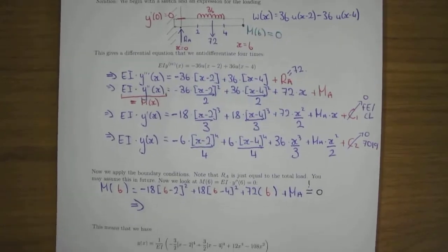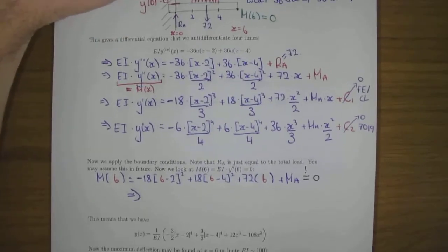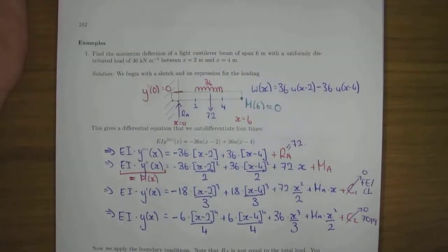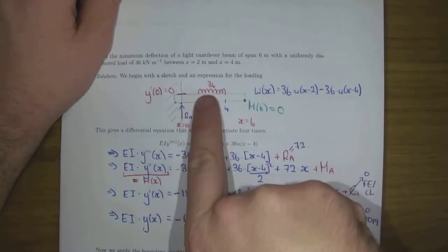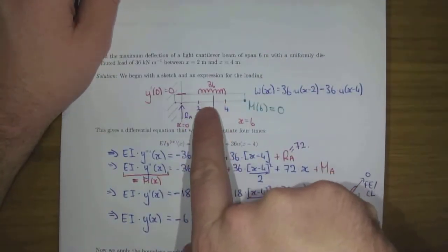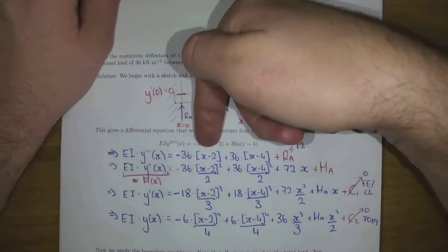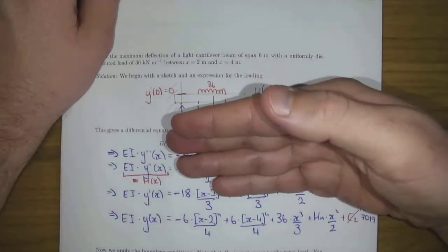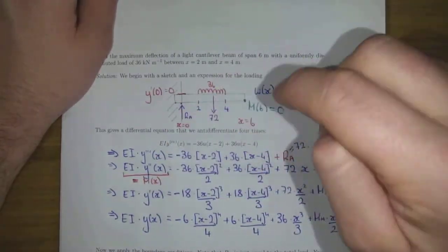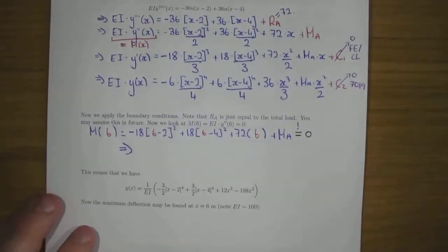Now there is an alternative, as I mentioned on the previous page, about balancing the sum of the forces and the sum of the moments. So if you do know this theory and you end up with the right answer, I'm quite happy. I'm not happy though to use your theory, which means your formulas, to just find the maximum deflection. But if you want to say, okay, in terms of bending moment, this is the same as a point load of 72 at x equal to 3. So it'll be a bending moment of 216, 3 by 72. So the MA, to balance the moments, because it's in equilibrium, otherwise it's rotating, must be minus 216. So we're going to find minus 216. Or I'll look like an idiot if we don't.